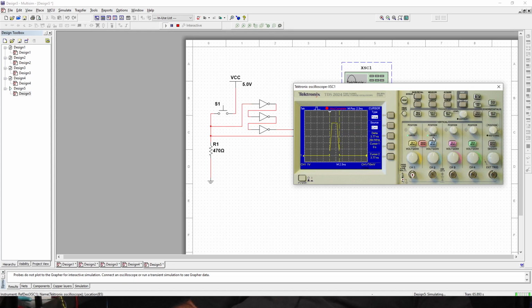There we go. It sits at 3.77 nanoseconds with reference to 0. And over here we have the delta between these two cursors. Delta is the change, the difference between these two. Of course, 3.77 minus 0 is going to be 3.77. So it looks like it takes 3.77 nanoseconds from when the pulse completely begins to when it completely ends.